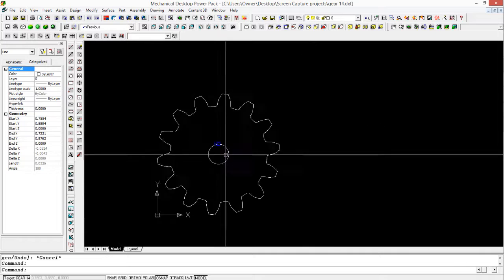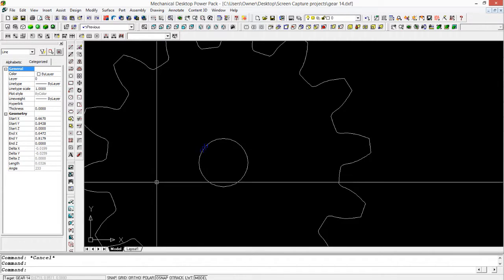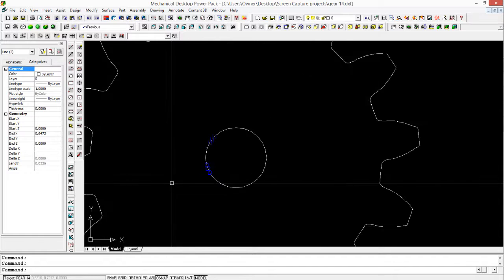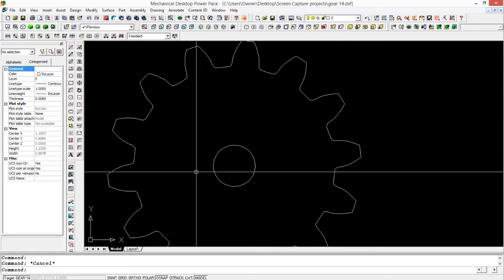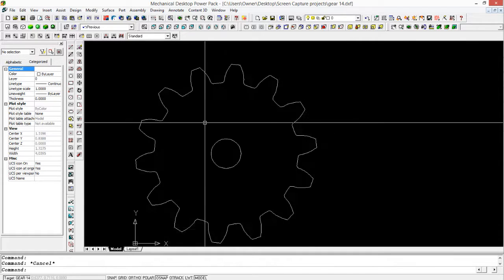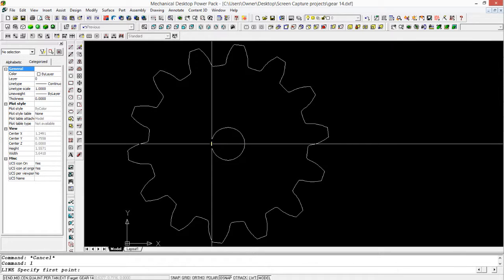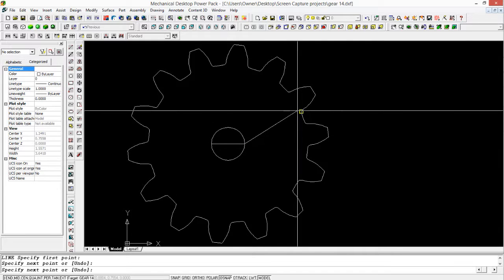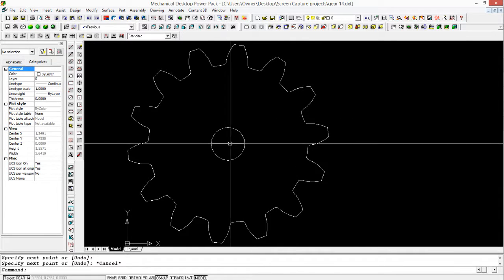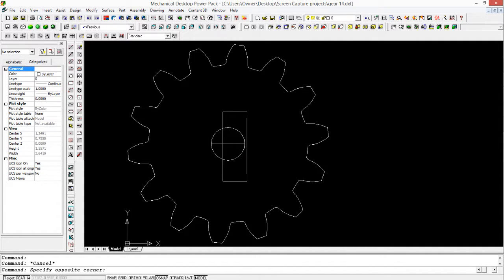But look here. Now we've got a polyline for our outer perimeter, but look, our circle is a whole series of little short lines. And that's not going to work well for us. So this is what I do to locate the exact dead center of that. I just draw a straight line. I pick a point that's approximately dead across, and draw me a little line that gives me a place that's got a center. And then I can just get rid of all these little short lines.